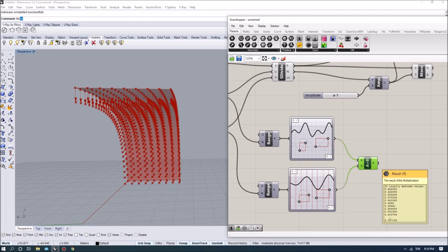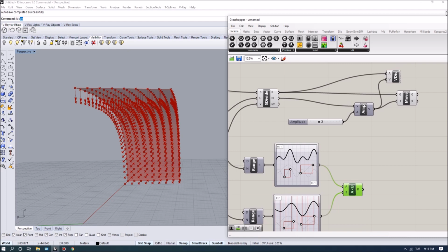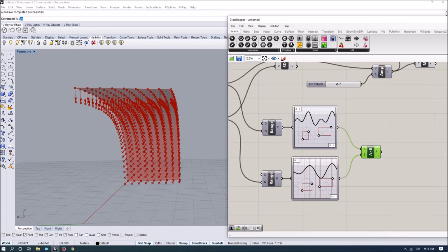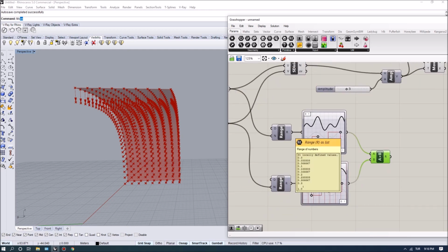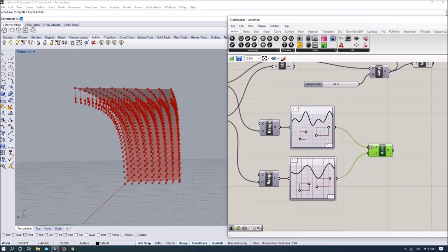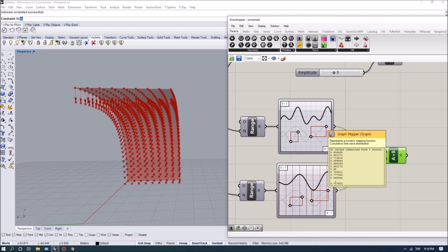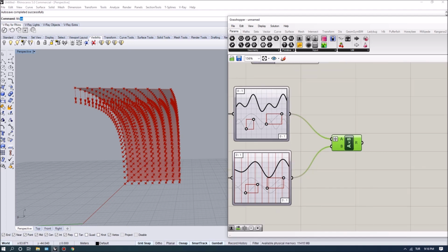But when I multiply them directly, you see that we actually get 31 values. And here, if you look at the data, we have 279 values. So I need a data set that somehow mimics this lists within lists, right? So I need 31 lists containing 9 values each. And to achieve that, we can simply graft one of these streams, and grafting it will use this amount to multiply it uniformly with every amount in the bottom list, right?